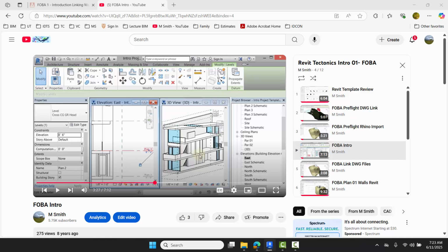So the other thing that you can look at is the level for plan 3, because this floor is on level plan 3. You can see over here, this is on plan 3. If I change plan 3 and drop it, whoops, these little things are the bane of my existence. Drop it to, let's say, 17 feet. You're going to see the entire floor move down, right? So you can see it getting shorter, or if I undo that, getting taller. So the way that it flexes the model makes a big difference.